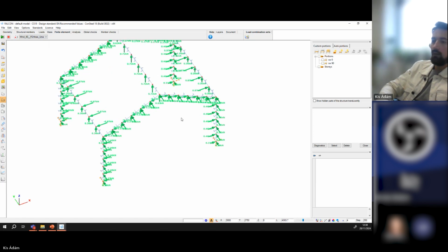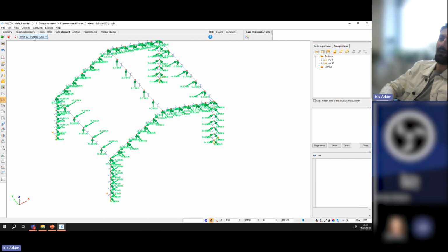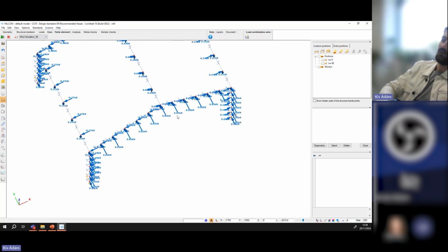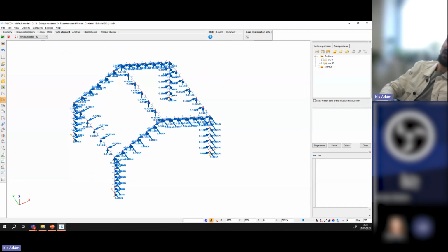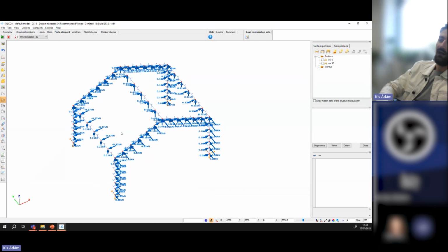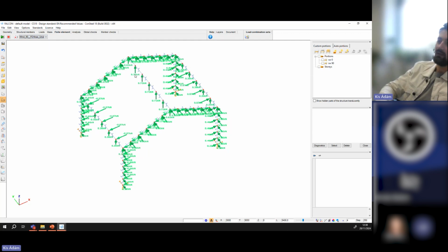As nodal loads on my beam members. So for example, for a 90-degree direction, I have 0.62 kilonewton for every finite element, which is similar for simulation. However, for suctions, the values are smaller, but the idea is that these are easily comparable. And in general, for the windward side, the results are really appropriate to Eurocode values.